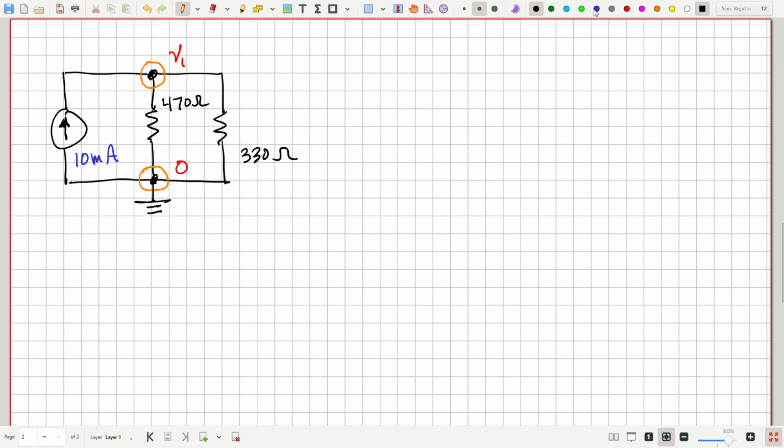Okay, so this is the basis of the node voltage method. We go to every essential node other than the reference, and we say, what is the sum of the currents flowing out of that node? Well, in this case, there would be three currents flowing out. And write those. So KCL at this node with voltage V1.